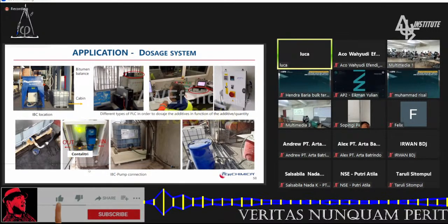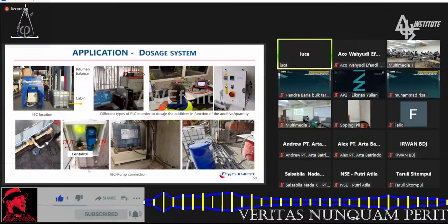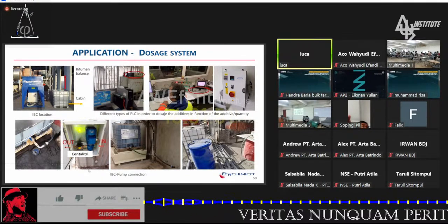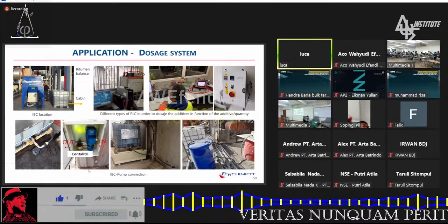to the system in the asphalt plant. Usually we add it in the bitumen. Why? Because we are not using 100%. With 50%, we prefer to use the bitumen like a vehicle to spread the rejuvenator homogeneously in the mixer.